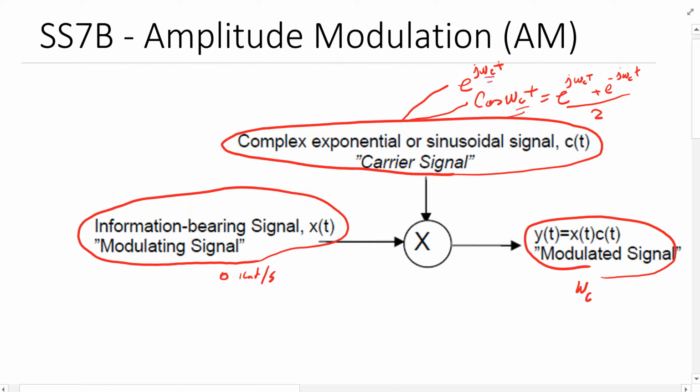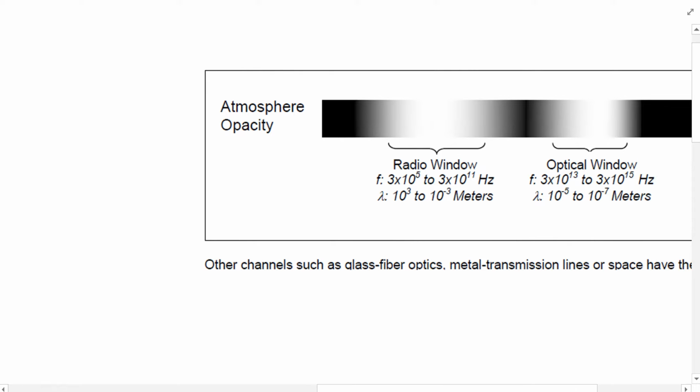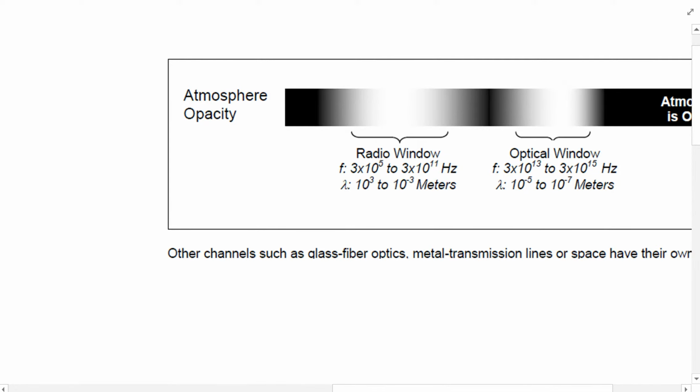Now, why do we want to do this? If voice, for example, is going to be from 0 to 20 kilohertz, it's going to be very low. It's going to be through the black area, which, if you recall, is the high impedance area, so nothing is going to make it through very far. Most of it is going to be consumed by the impedance of the air. So I really would like to be here, even though my signal is sitting in here. My carrier frequency allows me to move it here, so I'm in the low Z, the low impedance area.